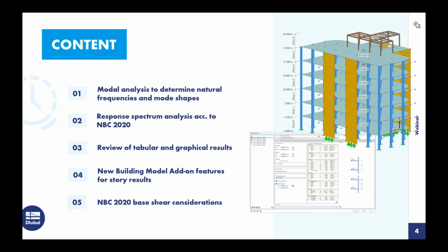As far as the content over the next hour today, we will begin with a modal analysis of the structure shown over here on the right-hand side to determine the natural frequencies and mode shapes. We'll then move on to a response spectrum analysis, in particular according to the NBC 2020. For both the modal and the response spectrum analysis, we will review the results both in graphical and tabular form.